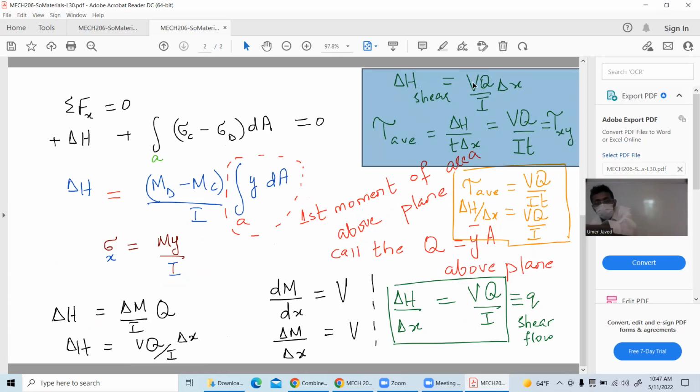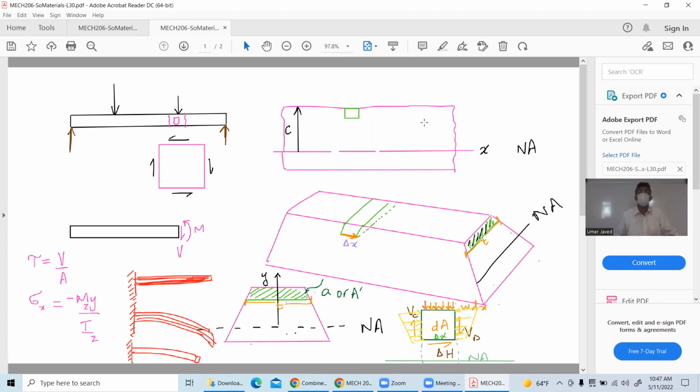Now you tell me, what is V? Of course, that's a force, but you have to tell me which force. The load that you are applying, what do you call it? The transverse? I think transverse is the right English. Well, like this is a beam. That's the load that you're applying. What is the V? You know how to find the V. You make a cut, you throw the chunk away, you find the V. The transverse here. So that's the V that you all find, right?